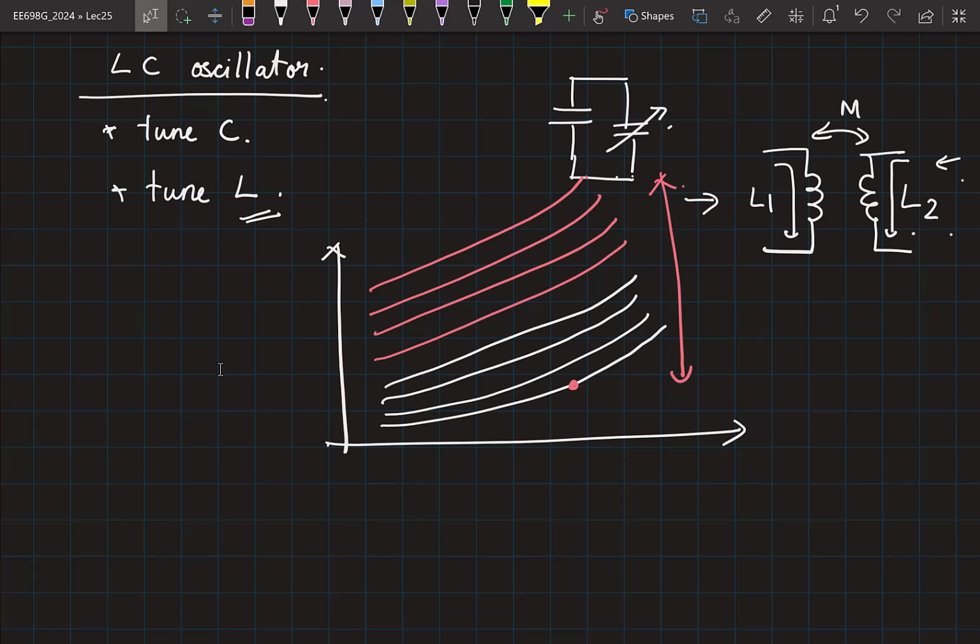Sort of like a binary search, right? So you will need some mechanism to detect the oscillator's frequency in a coarse manner. And then based on whether it is larger or smaller, you need to keep changing the code. So in 619, some of you have implemented a frequency lock loop, where you detected the frequency just by monitoring the clock for a long period. Same algorithm you can use.